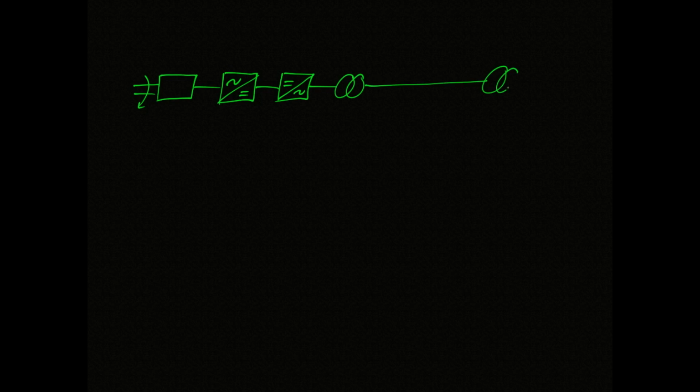And we will draw the transformer as two linked circles like that. If you've studied electronics before, you may have seen transformers that look like this. But just know that they're the same thing. Now, the reason we need transformers is because this wire is long. That pumped hydro system is 5 miles away from town. In order to make the system work, we had two choices. We could install really thick wire, or we could run a low current, high voltage system.